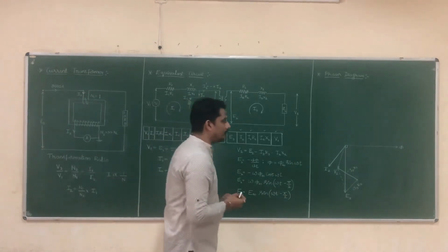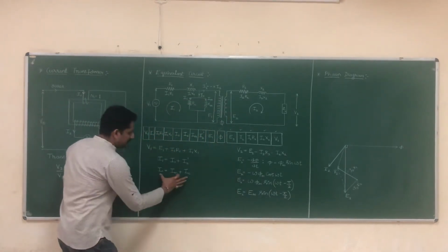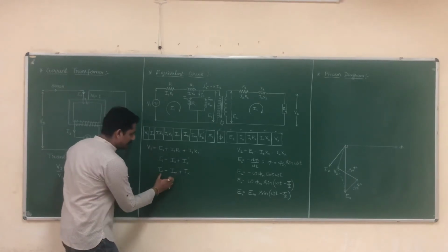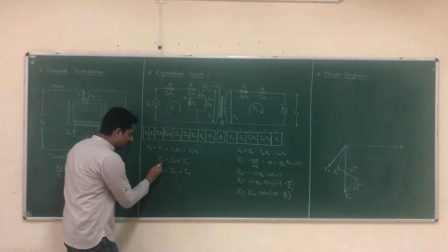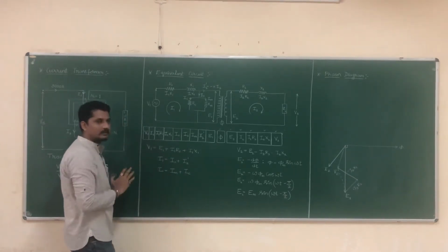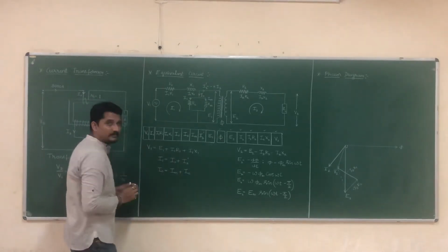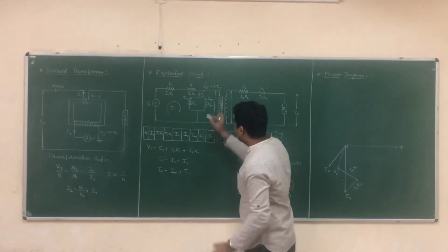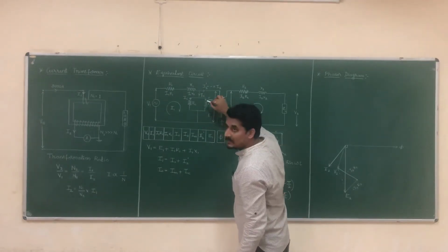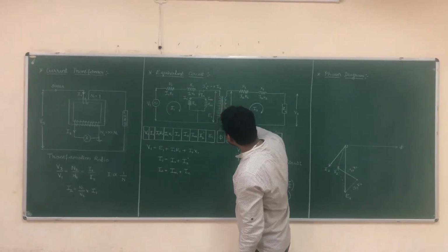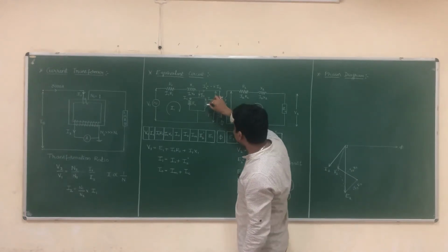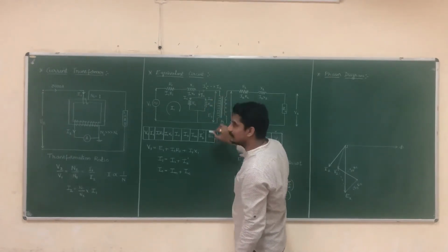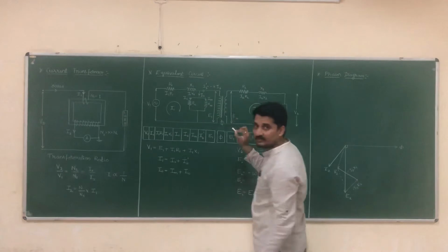Okay. Now first we need to find this I0, because from this I0 I will be getting I1, and from this I1 I will be getting V1. So I0 is equal to Im plus Ic, right? This I0 is equal to Im plus Ic. And out of these two parameters, this MMF links with the flux. This MMF, magnetomotive force, links with the flux. So this is responsible for this flux phi.